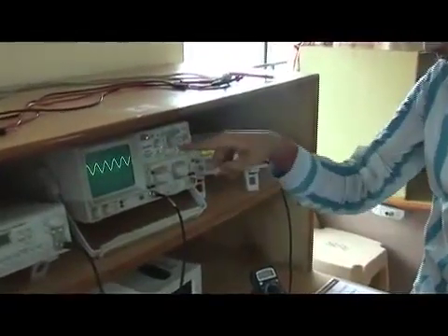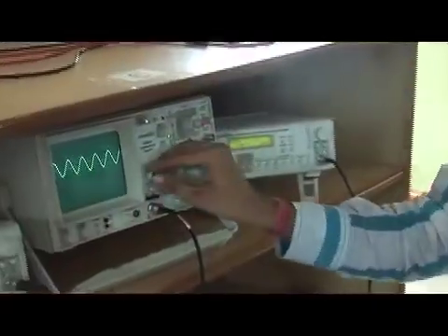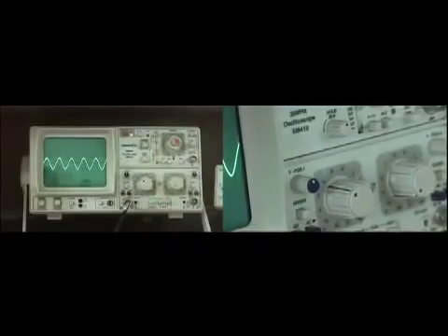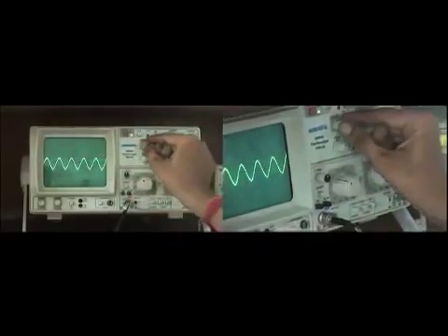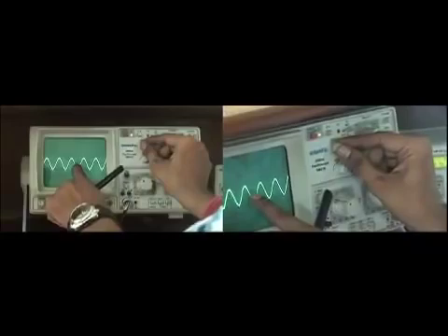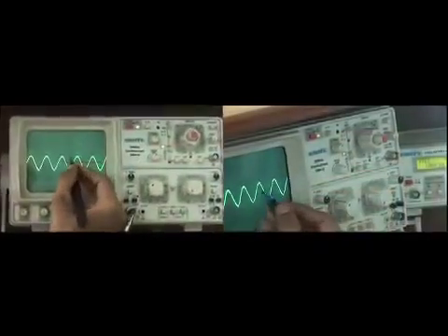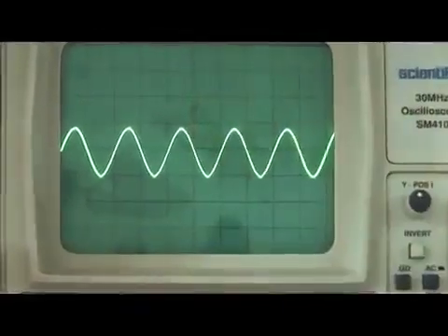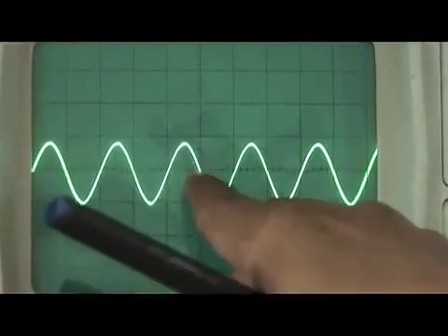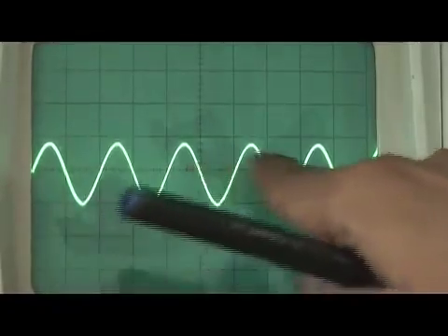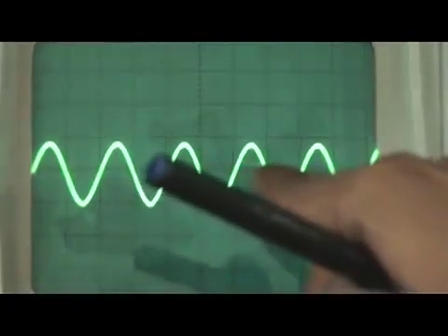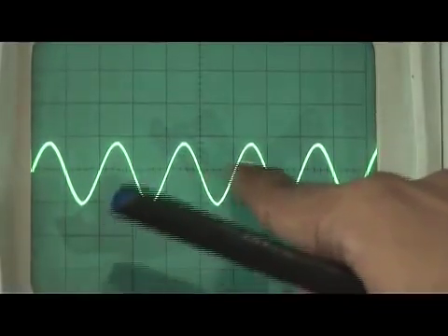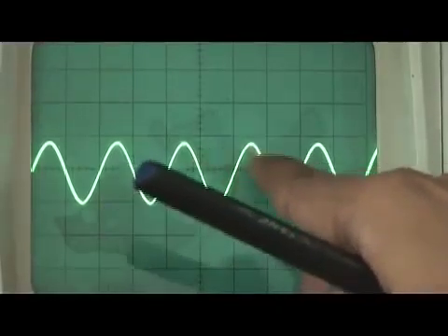Next we move to how to calculate the frequency. Again, make it ground, bring it to the center of the line, release the ground, and set this y-axis in such a way that you can easily count one cycle. If I set it here, from this point to here is one complete cycle. How many blocks does it require? It requires almost 2, so let us take it as 2. So it is 1 block, 2 blocks. To complete one cycle it requires 2 blocks.